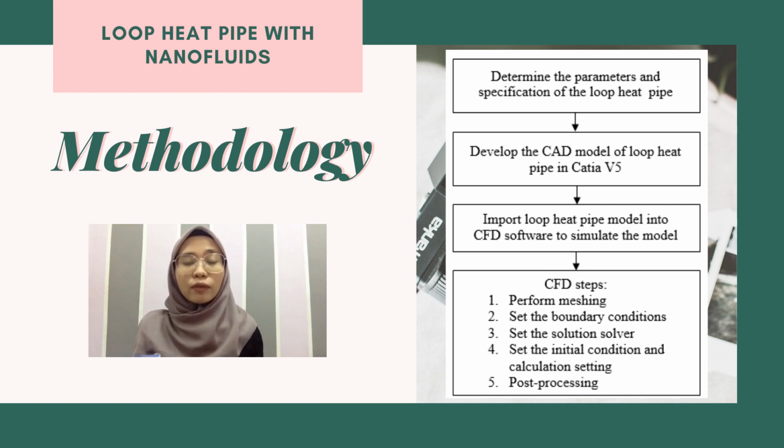Second, we will set the boundary conditions, which consist of the velocity and temperature at the inlet, pressure at the outlet, heat transfer coefficient at the surface of fins, and heat flux in the bottom plates. Third, we'll set the solution solver, where we use the volume of fluid method. Fourth, set the initial condition and calculation settings. And fifth, we will do post-processing for the model.